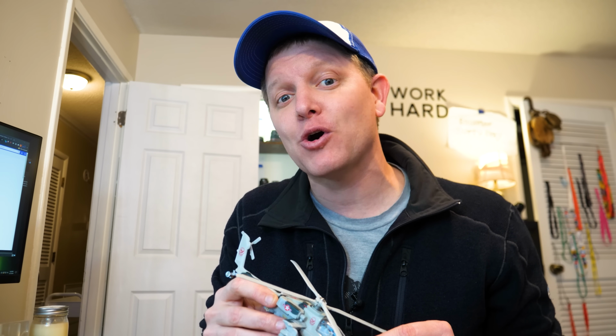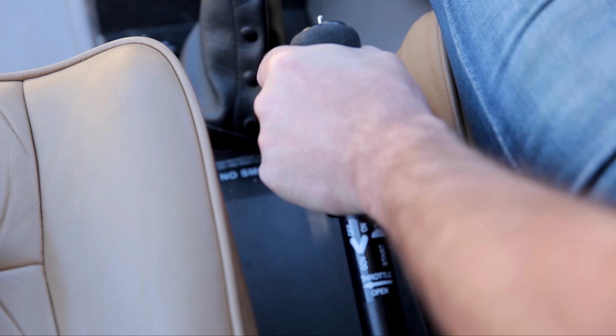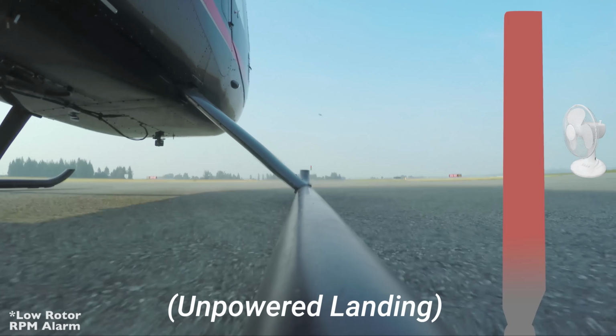Another problem they had with helicopters is the way you had to do the test. For example, if you're just hovering above the ground and you're descending in a straight line, that's a very difficult thing when you're close to the ground because you're inside what's called dead man's curve. Basically, in a helicopter, you want to have enough altitude or velocity to be able to auto-rotate to the ground if you lose power. I made another Smarter Everyday video about that if you want to check it out. But long story short, helicopters could be dangerous for this specific test application.